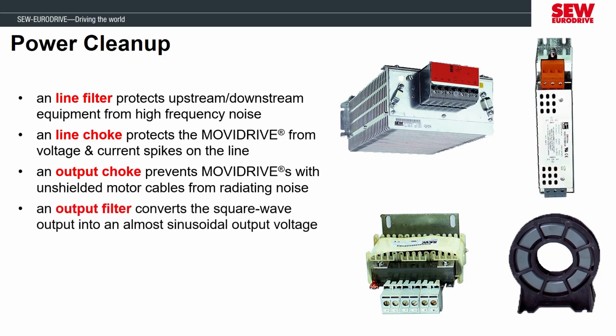The output filter is helpful in applications with long motor cable runs. Some applications with long motor cables or shielded cable can cause recharge currents high enough to damage the inverter's transistors. Also, voltages can peak inside the motor winding because of the long motor cable, which stresses the motor's insulation. The output filter is designed to reduce these peaks seen in the transistors and at the motor windings.